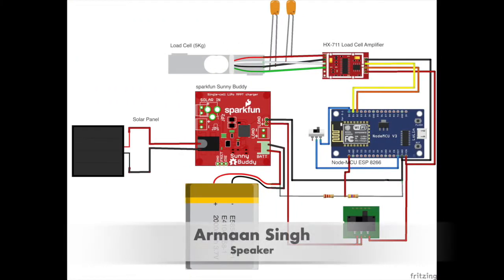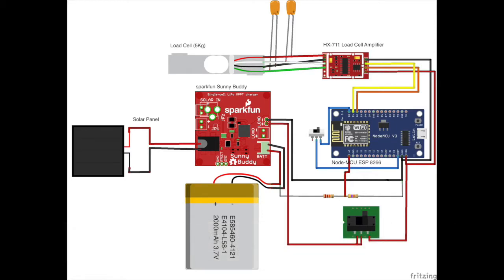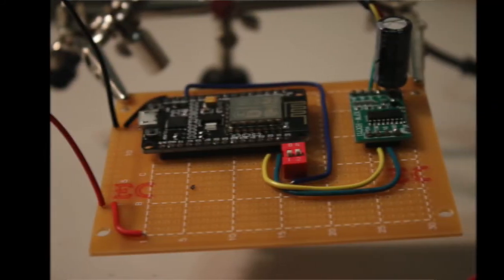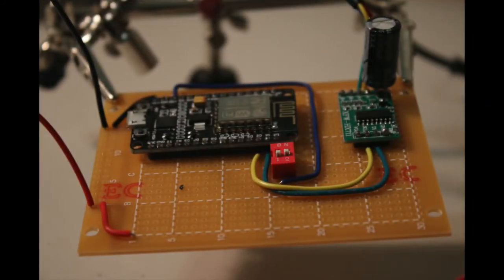The main functions of the electrical circuit for FlowMo include measuring load cell readings, communicating the data over a wireless connection, and sustaining the device's power requirements over a long period of time. The main components of this circuit include a Node MCU microcontroller and a load cell connected to an amplifier. Capacitors are included to reduce noise in the amplified signal, and convenient control features such as main power buttons and dip switches are built in to allow the operators to easily control and adjust the behavior of the module. Additional electrical components for power management will be introduced by Jasper shortly.